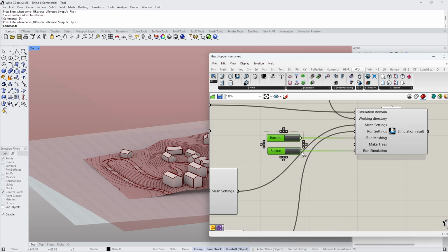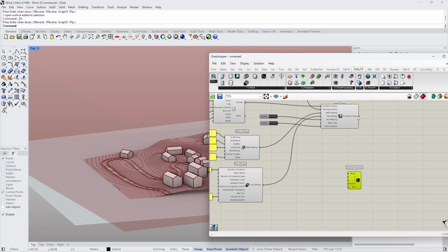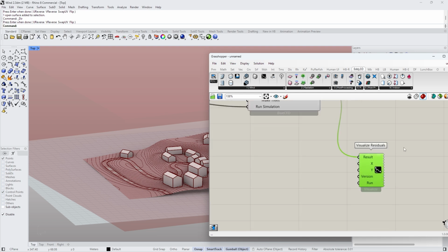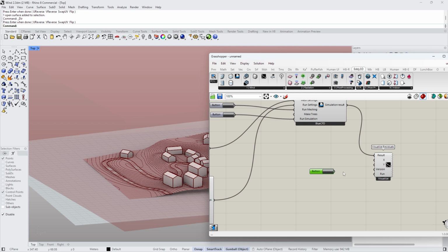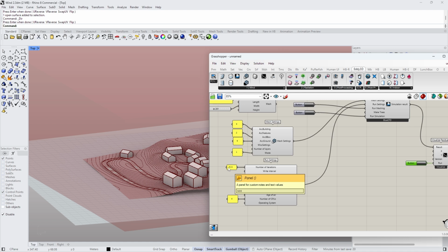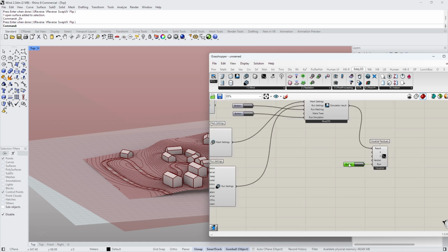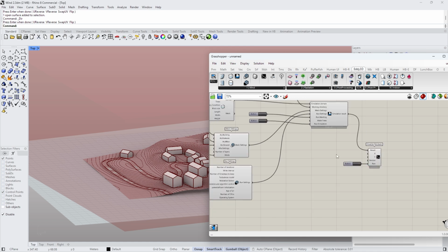And before I run anything here, I will set up 2 other things. One is the residuals. The residuals help me to monitor how accurate my calculation ran, so I can make adjustments if I need to. That's basically it will draw a graph for these iterations and will tell me if my analysis or calculation was successful. It also shows the accuracy at the end. So it shows how much error is still left after each iteration, to be very precise.